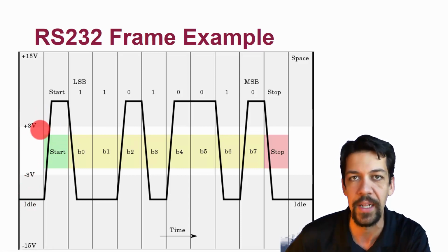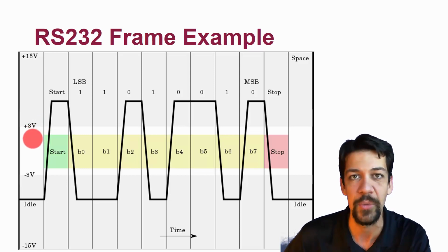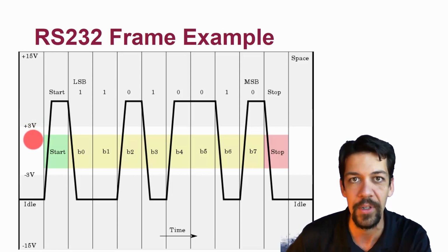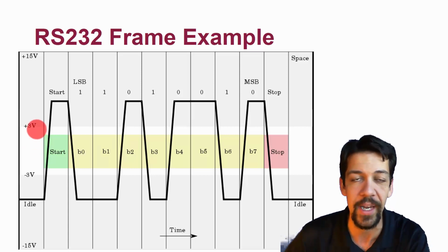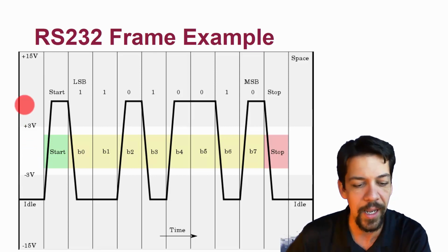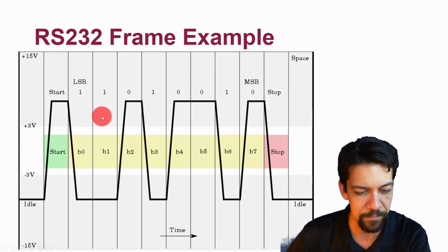That produces a lot of electrical difficulties, and that's why one of the devices we looked at earlier this semester was the Max 232 level shifter, because we can convert between any two levels of RS232 protocol using that device. So if we have a 5 volt device that needs to talk to this bipolar plus minus 5 volt, we can use that device to communicate between them.